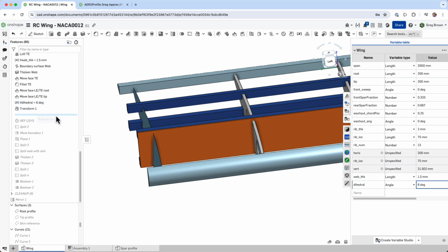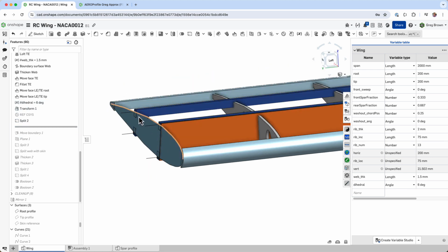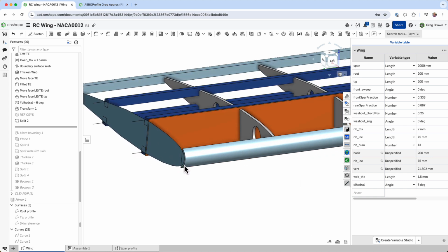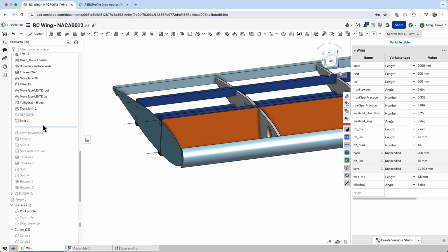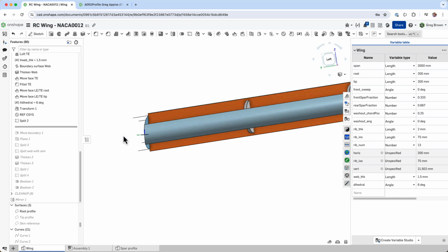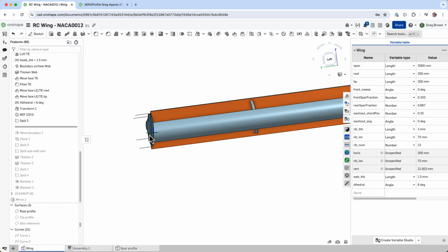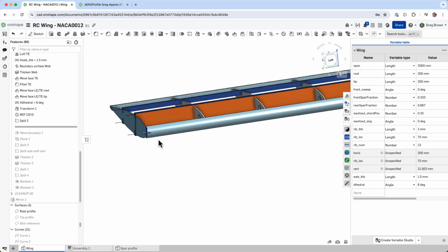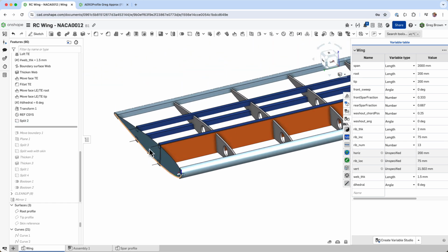And what I do then is split, and you see why I overbuilt these things: I wanted to split them all back to that plane there. That's why it's there. Now I've got this other mate connector which is going to act as a reference coordinate system so that I can place the wing in the upright position with its dihedral taken care of. So that's that, and now we've got a nice clean split across here.